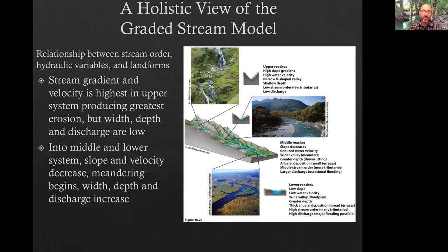And you start to see more tributaries connecting, streams widening, carrying more sediment. And as it slows down, because at a confluence you have two vector forces intersecting with each other and then going in a totally opposite direction. So just like Hot Wheels slamming into each other at an angle, they slow down a little bit. So the water in those channels where it has a confluence slows down, material drops out, lessening the slope even more over time.